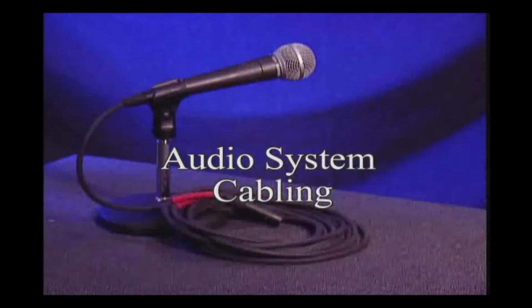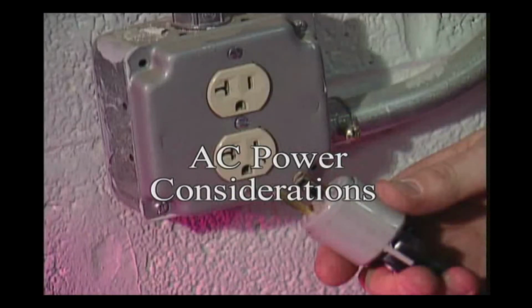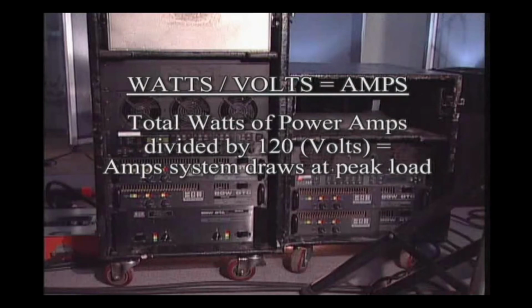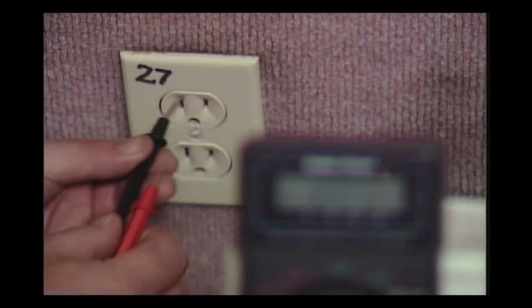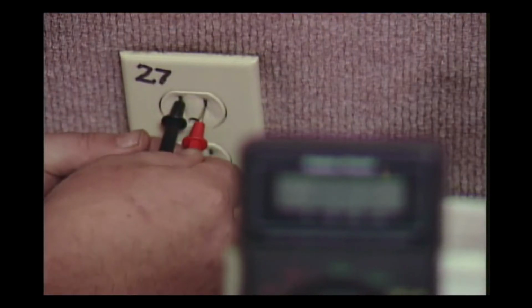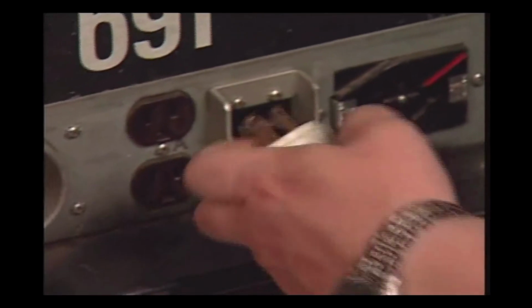When it comes to grounding, there are 4 areas of consideration. The first is the AC power outlets. Determine the power demands for your system by adding the total wattage from your amps and dividing by 120. The resulting figure is the amps necessary to power your system under peak load, and will give you a rough idea of how many circuits should be set aside. Buy a multimeter and use it to check the outlets on the circuits you'll be using. If a fault is found, don't use that outlet. Always use 3-prong AC plugs without adapters to plug into.